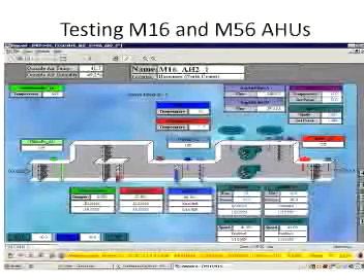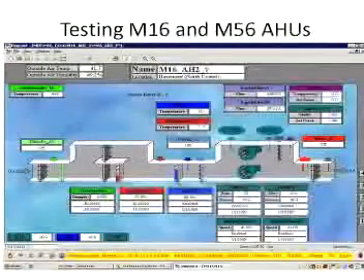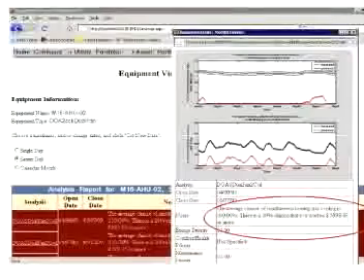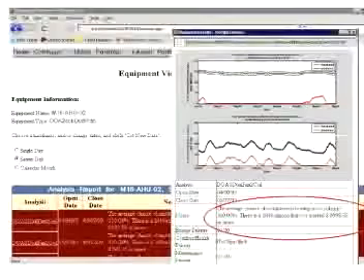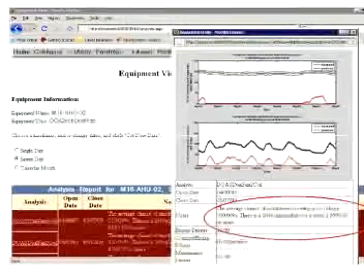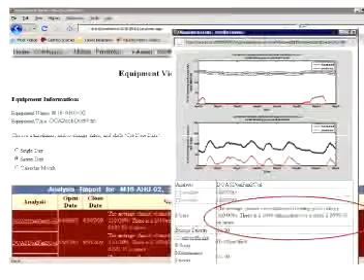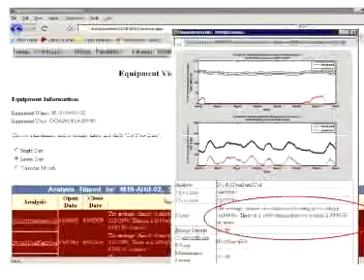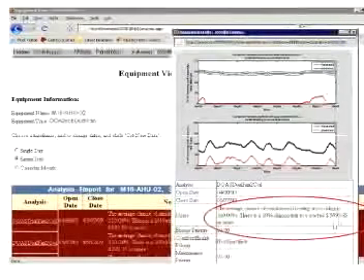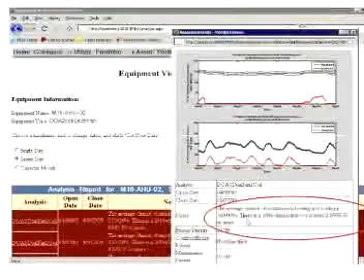This is just sort of a schematic of what the control for a large building at MIT looks like. This is the output of the software which he's designed, and the main goal of the software is to identify to the maintenance people the 10 most important things going wrong in your building, and then using probability to estimate the energy and the cost associated with that. So in this case, what I've circled down on the right-hand side here is just an output from that, which says, in this particular case, there's a 20% chance that you've wasted almost $6,000 or more per year because of improper operation of your equipment.